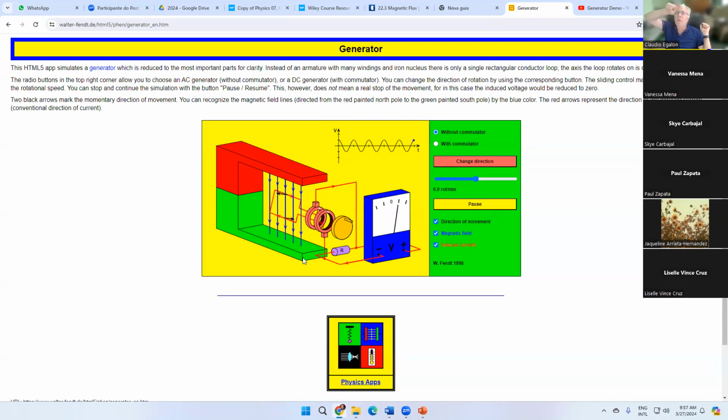The current goes back and forth in the circuit. Okay, so just try to visualize the current in, for instance, the DC circuit, the direct current circuit. In a direct current circuit, the current just flows in a single direction, either clockwise or counterclockwise. In an AC circuit, the power supply is the generator itself. The current goes in one direction and then reverses direction, back and forth at a given frequency. That's the important difference between a DC circuit and an AC circuit. The change in voltage is sinusoidal because we are cranking this device at a constant angular velocity. If the angular velocity weren't constant, then the voltage would change differently.